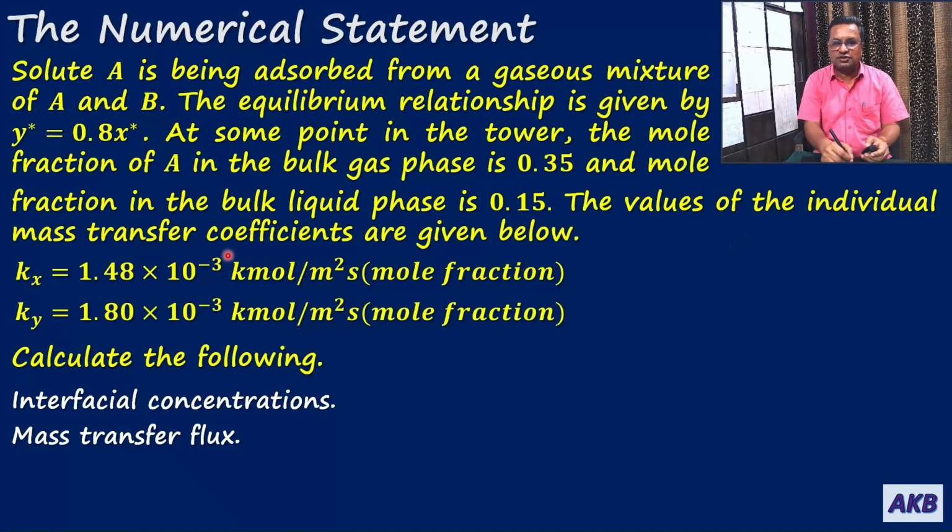Kx is 1.48 into 10 to the power minus 3 kilomole per meter square per second per mole fraction. Ky is 1.80 into 10 to the power minus 3 kilomole per meter square per second per mole fraction. And we are supposed to determine the interfacial concentrations and then the mass transfer flux. I hope what is given in the numerical statement is clear to you.